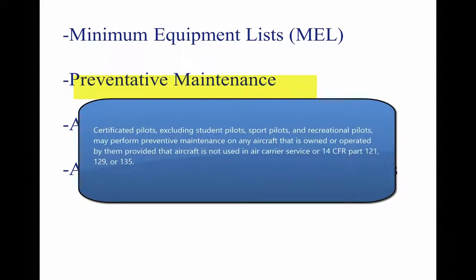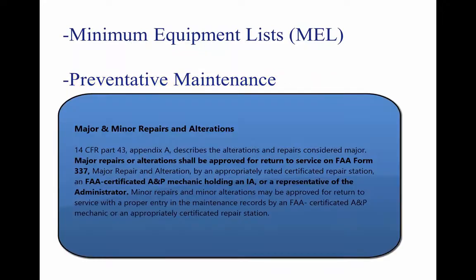Certificated pilots, excluding student pilots, sport pilots, and recreational pilots, may perform preventive maintenance on any aircraft that is owned or operated by them, provided that aircraft is not used in air carrier service or 14 CFR Part 121, 129, or 135.